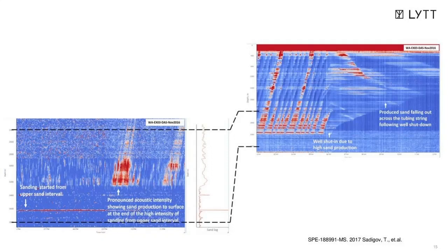And then we see the sand is lifted and traveling through the tubing in the upper completion to the surface. So we open this depth interval further up all the way to surface. Then you can clearly see sand lifted, traveling through the upper completion tubing all the way to surface in the form of slugs. So it's being lifted in a periodic way.